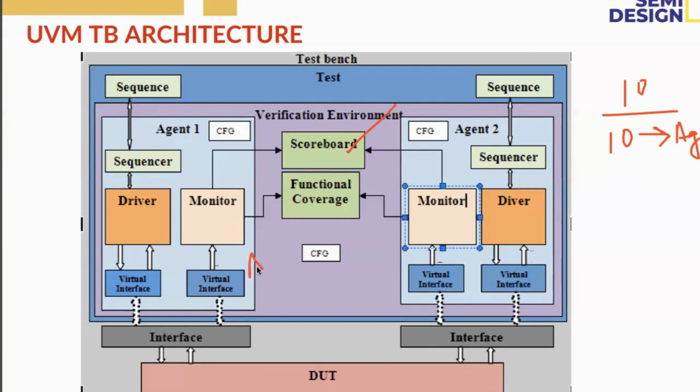Suppose here there is an APB and there is an I2C. Before, you have worked on APB and I2C, right? There you generated the scoreboard separately in the TB for APB, and for I2C you developed it in its TB itself. So separately you can develop like that. Otherwise, you can create one overall scoreboard and write different scenarios for each IP.